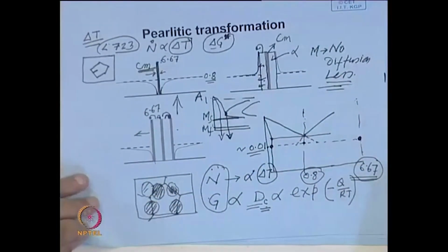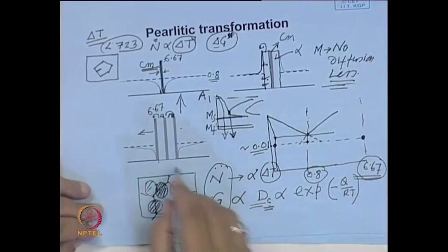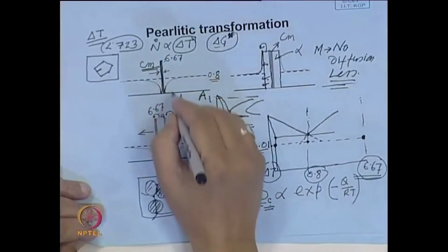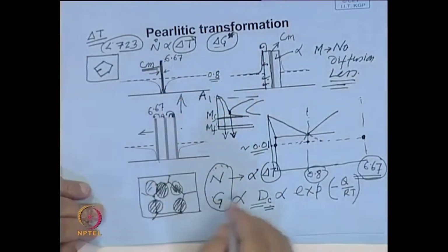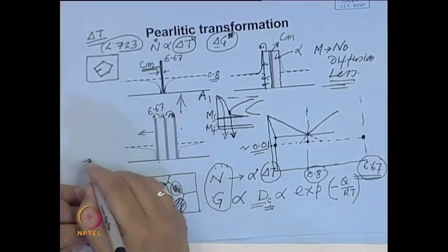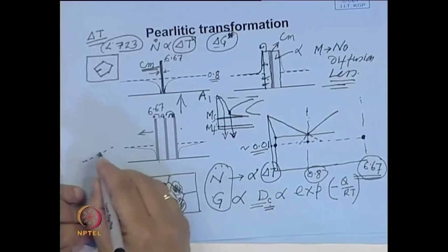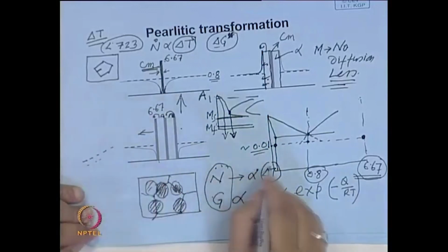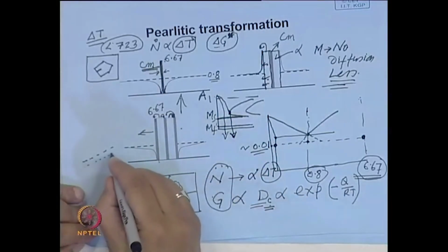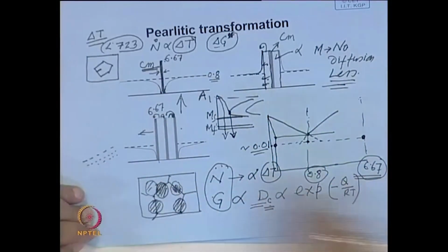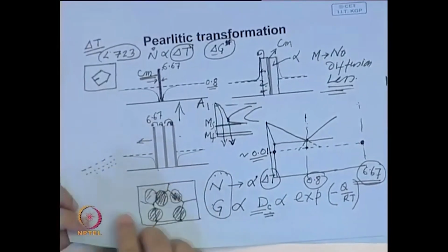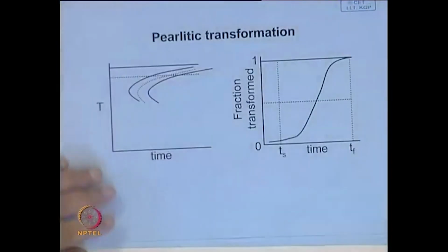Whereas, in the case of a bainite structure, there is diffusion, but you can see in pearlite that the carbon atom moves over a large distance, and in bainite the carbon atom does not have to move a large distance. And so, that is why at a lower temperature when bainite forms, you have such a finer structure, such small platelets of cementite or epsilon carbides. There the diffusion distance is much less.